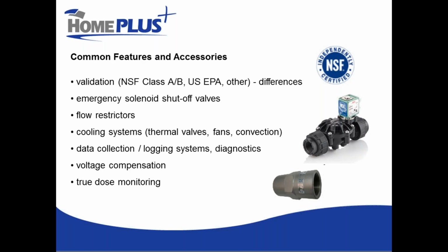Some other accessories, most of the time the health authority will require that the UV unit be equipped with an emergency solenoid shutoff valve. That valve is designed to close and prevent water flow if there's ever an alarm condition. An alarm condition can occur if the UV transmittance drops too low, such that a safe dose can no longer be maintained, or if the lamp burns out, or if there's a power failure.